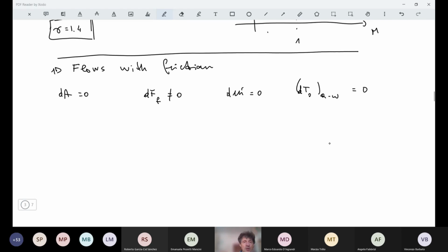So again, one driving potential. And in this case, d dot m is equal to 0, so there will not be the contribution which is present in all equations by this driving potential. And so we see that actually in this case we will have SC equal to 0 and SM not. More specifically, SM is equal to minus dF over rho u squared A, where A is the area of the cross section. That will be constant because we have no area change.